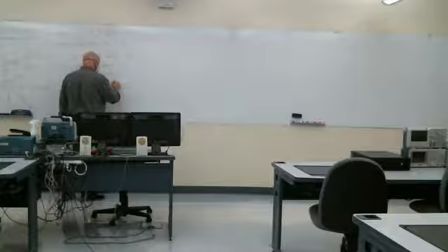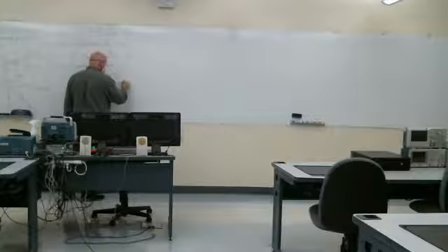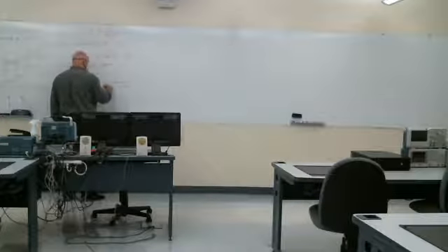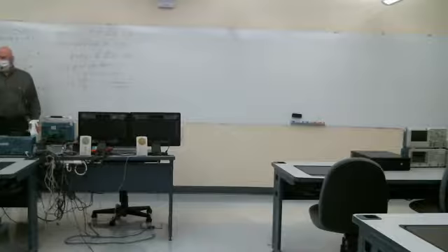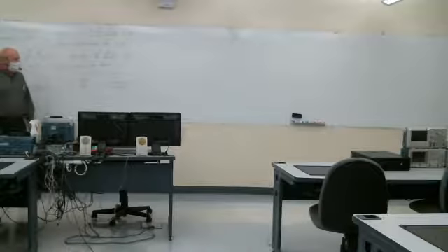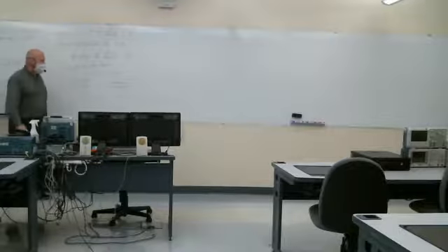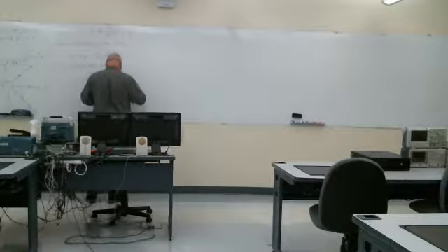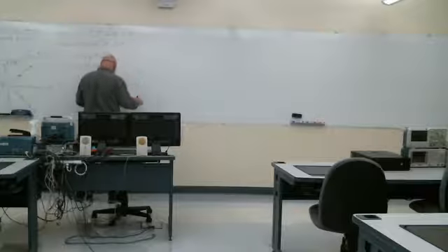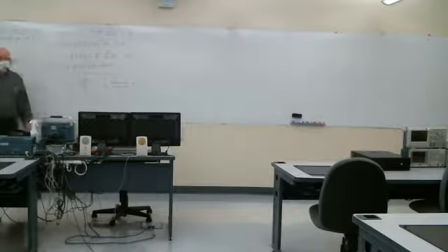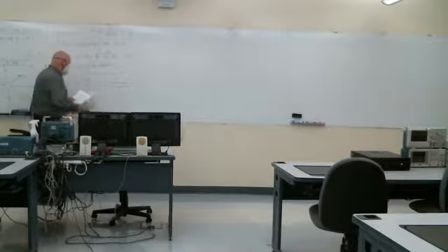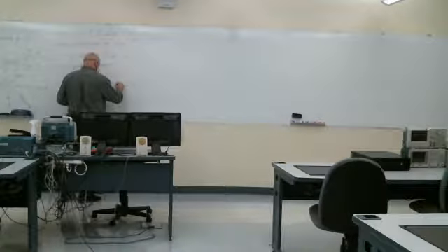what I'll get is an accumulation of positive charge on this plate, and an accumulation of negative charge here. So we'll have that voltage directly across the capacitor. It's in parallel with our voltage source. If this is a DC source, there's some initial current, but once the capacitor charges, there's no additional current flow. This is a distance d. We'll see later that inside the capacitor, we have a constant electric field that's set up.